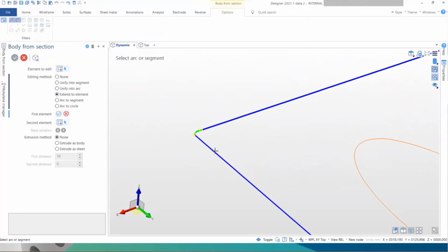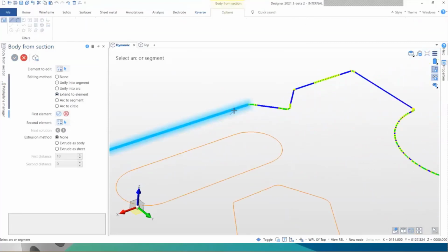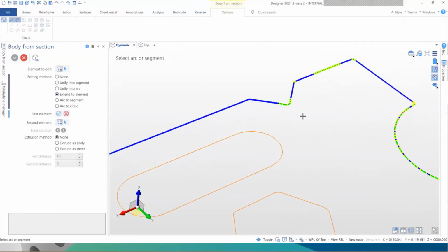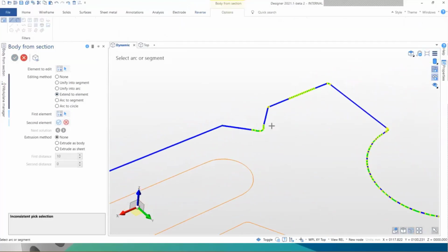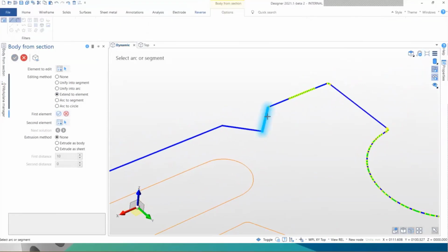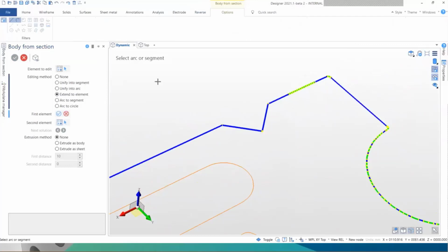And I'm just going to do that in all four of my corners, get those nice sharp corners, because we can add blends in later. That's fine. We've got this little feature which works quite similar. We'd rather work with a nice straight sharp corner rather than with some bad angles going on there.